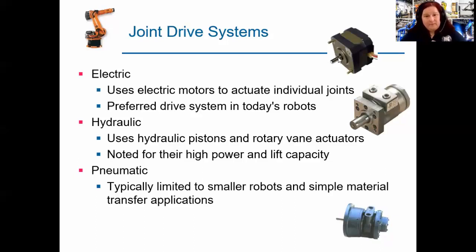They're working slower, but we do need many things to work slow sometimes, especially when we're lifting things. The reason we like hydraulics is that anytime you lift something, you have to hold it, and if you do it with hydraulic power, it's easier to maintain the same amount of force that you're holding something. Then in electrical, we need to put different kinds of signals, and sometimes the electrical motors don't have enough torque to hold something still for a longer time, especially if it's heavy.